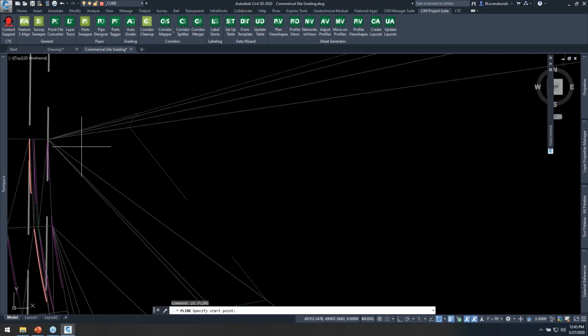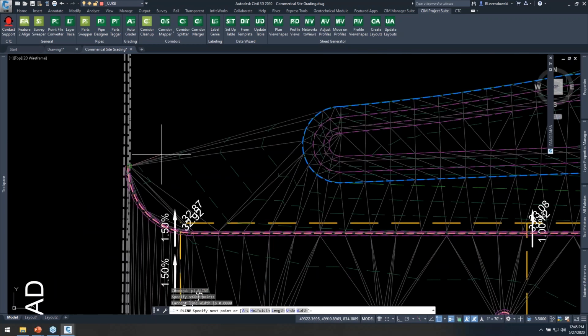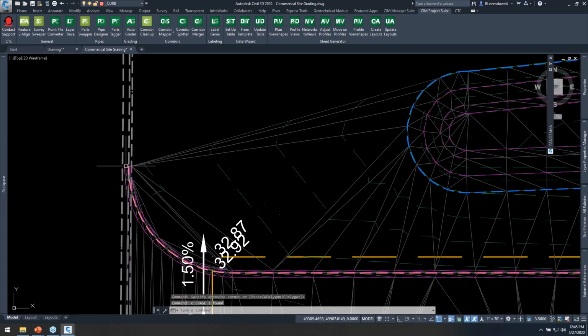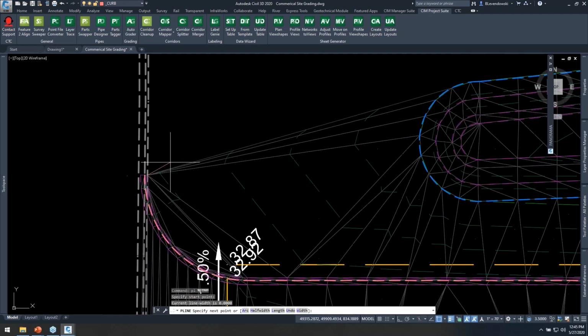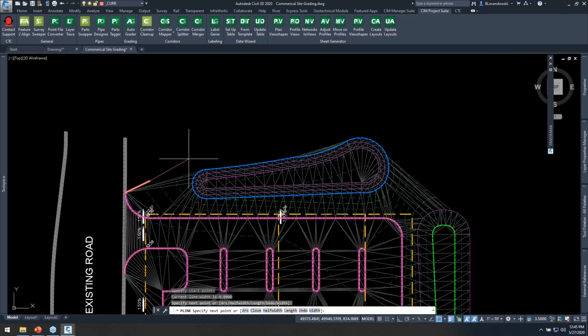So I'm going to give you an example here where I'm going to sketch out a polyline here that are kind of some initial grading limits. It's a way that I've liked to work often. And this isn't my daylight line, but perhaps it's maybe an initial kind of berm across my site, right?